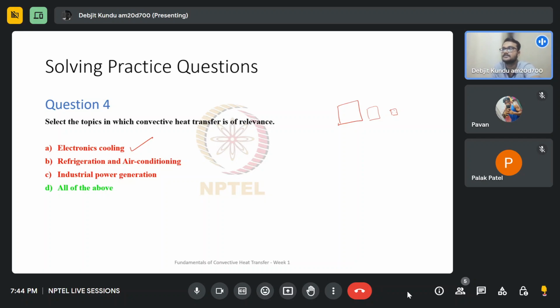Anyway, the main thing is these processors, as they are called, are getting smaller in size and more transistors are being embedded within them. And more transistors mean more electricity flows through it, and as a result, more heat is produced in it due to the simple effect of Joule's heating. And we know that at higher temperatures, the electronics start to degrade in their efficiency, as well as other functional properties are also lost.